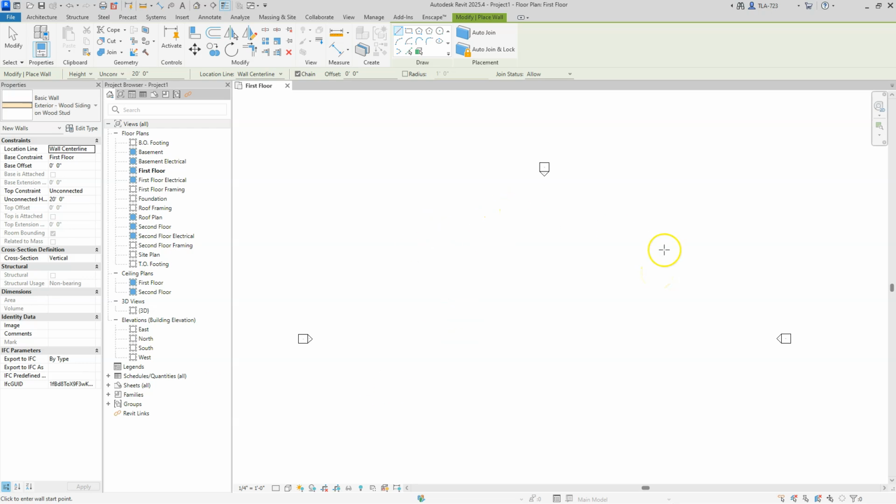So obviously it's important to understand the construction type that you're going to be working with and designing for in order to build the walls the way that they're supposed to be. It's really important that we model the project according to its real world size and real world materials. But with just those skills we learned just now, you can really model any type of wall. You can put any number of layers within that wall assembly, give them the thickness that would be appropriate, and you can create an exact copy of what it's supposed to be so that when you model it up in the computer, it matches what's going to be built in the real world.